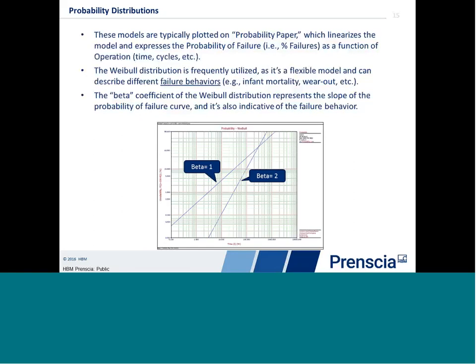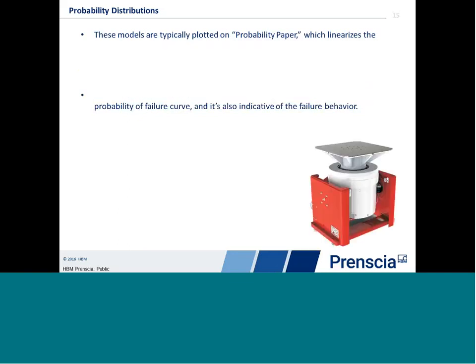This is important because we can use it to help understand how to build a test specification to demonstrate reliability. So remember this number, beta. We'll see it inside our ReliaSoft demonstration in just a minute. But before we dig into the software, I want you to think about where this distribution characteristic actually comes into play. Let's go back to our question of how we demonstrate our part being free of cracks after 4,000 service hour equivalents of loading, while also demonstrating reliability of 90% and a confidence of 90%. So how do we do this?